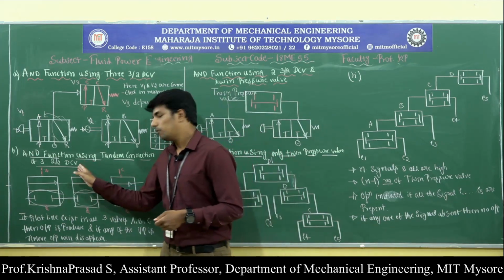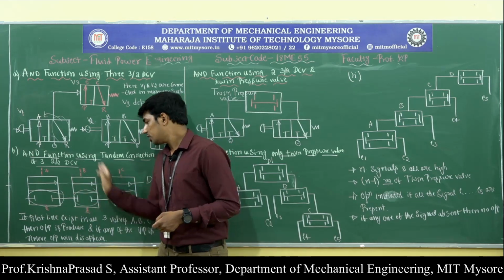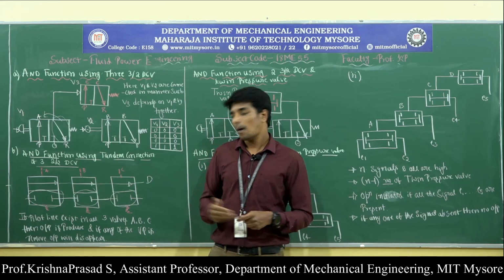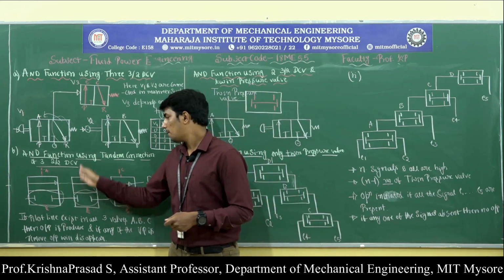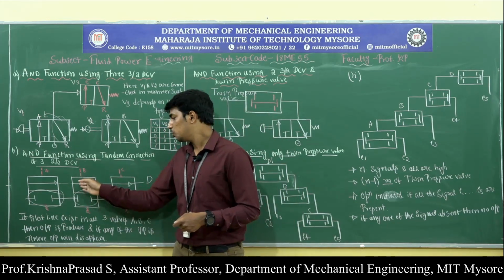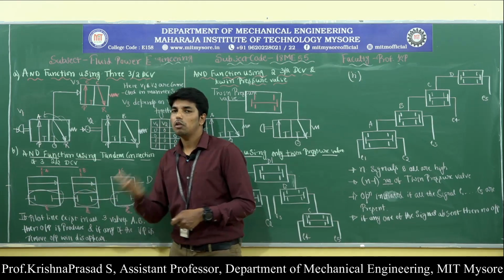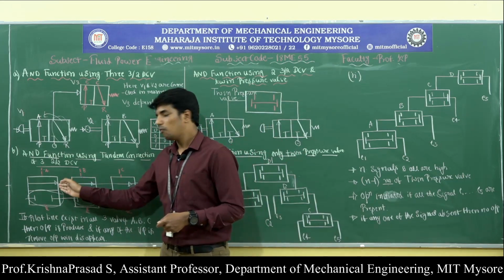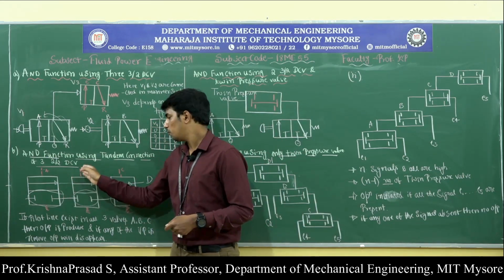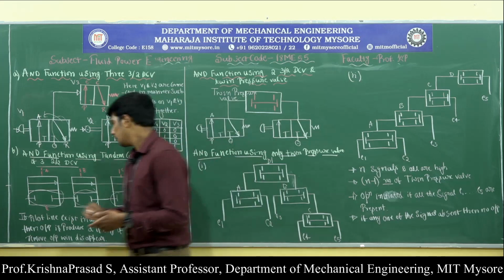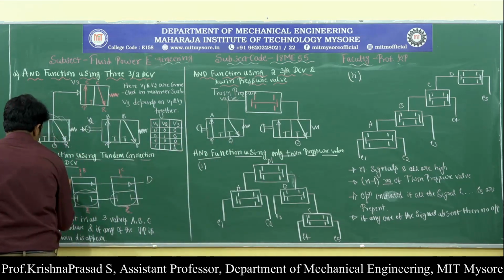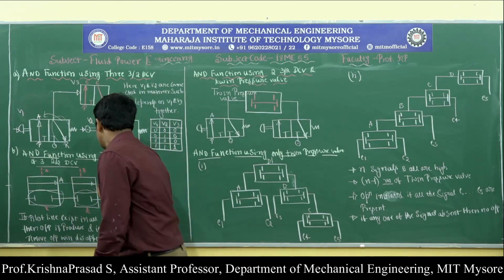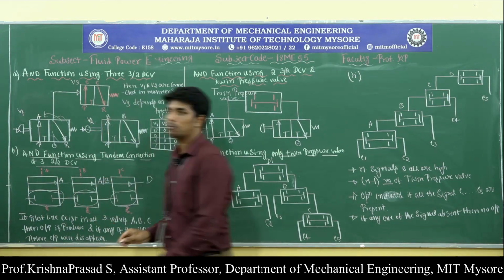Now if this second direction control valve is also activated with the help of the push button, then compressed air will also flow through the pilot line B, and this pushes the twin pressure valve exactly to the center. Then compressed air will flow from A to B, next it will flow from B to C. The compressed air operated from A will come to the second direction control valve, then it comes to the third direction control valve.